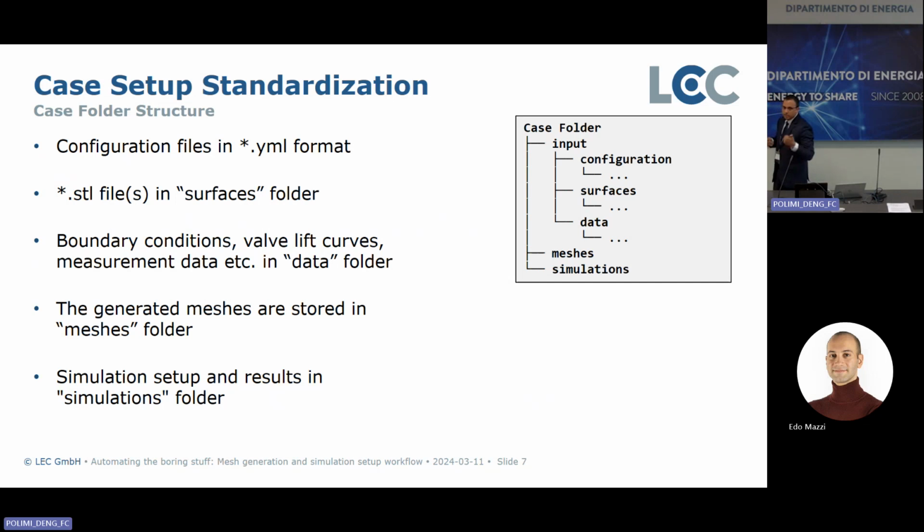Input data contains surfaces and all your data, for example, boundary conditions and initial conditions, valve lift curves, all these things. Then we generate a set of meshes. These meshes are then contained in the meshes folder, and then when the simulations are run, they are stored in the simulation folder.